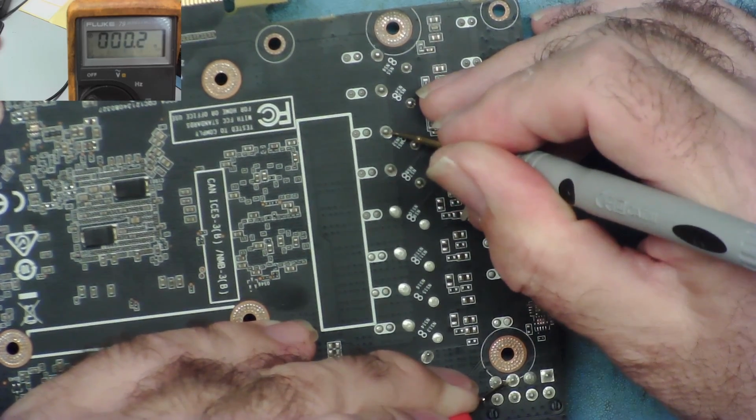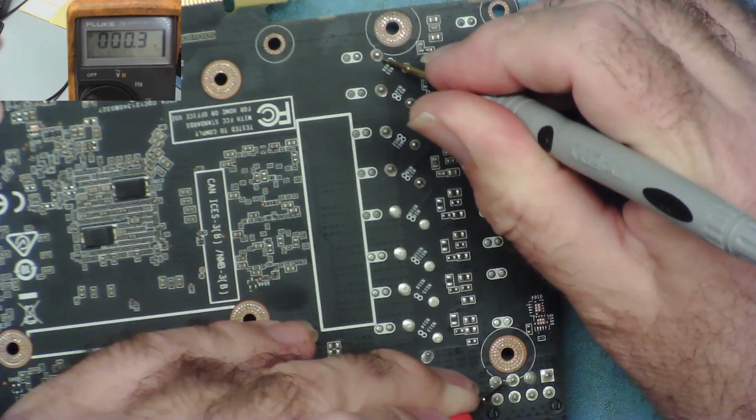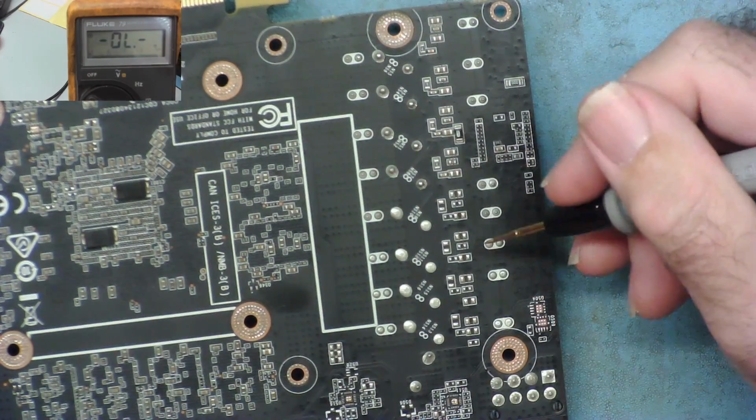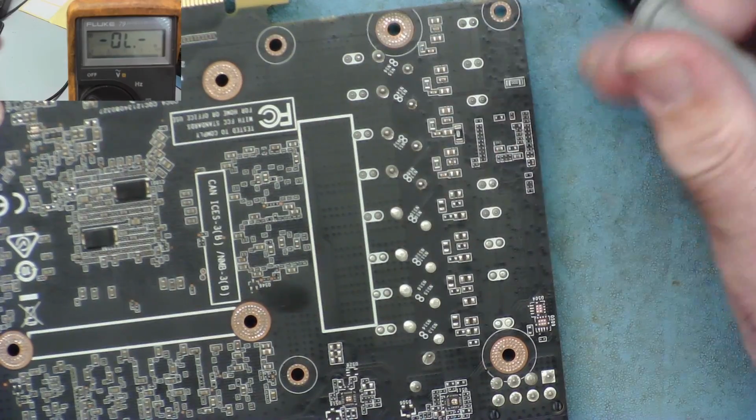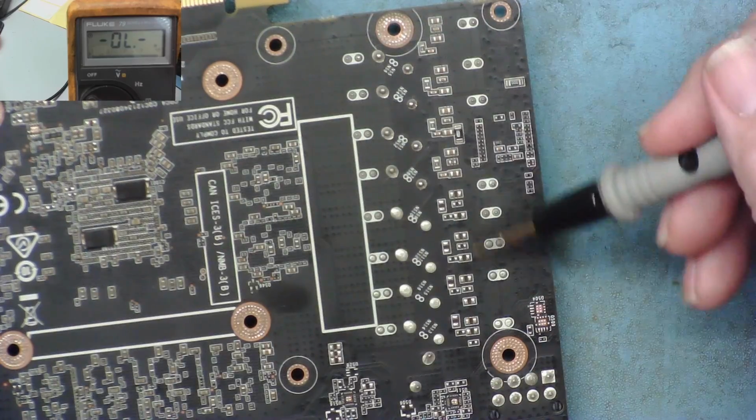So that multimeter is not going to tell me which of the coils has the short circuit high side MOSFET, which phase. But this multimeter can only read to 0.1 of an ohm. I have another multimeter which will read to 100th of an ohm, 0.01. So let's have a look to see if that can tell us which phase has a short circuit high side MOSFET.